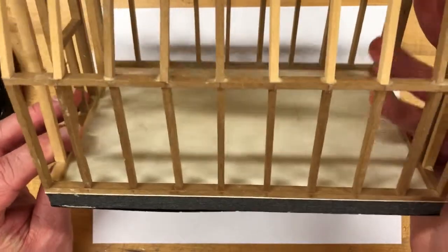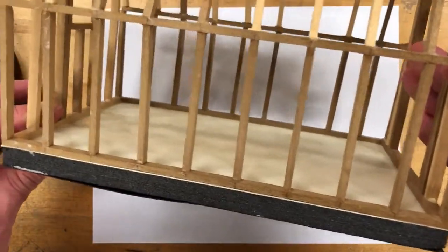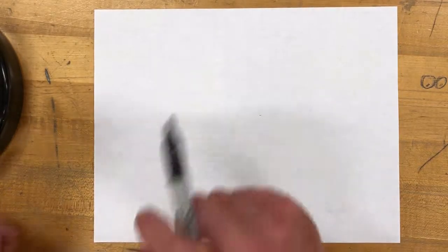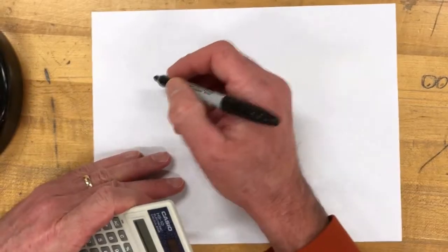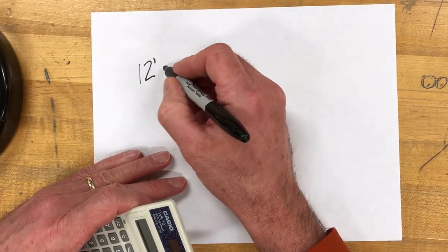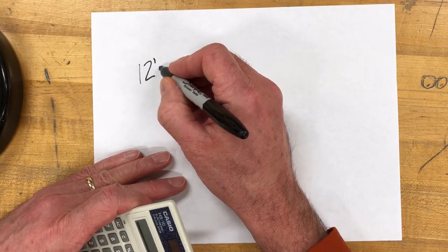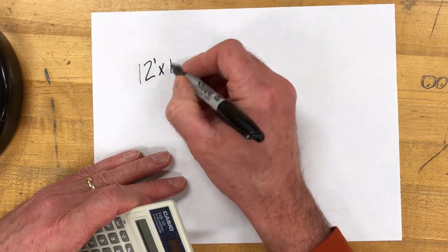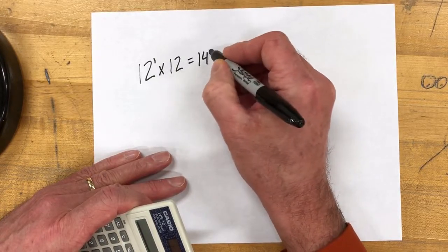Okay, as I said earlier, we're going to have a little bit of discussion about how many studs we're going to need along this wall system right here. The way we do that is we know that this wall system is 12 feet long, and that the stud spacing is exactly 16 inches apart. So we're going to have to do some quick calculations here. I know that the barn is 12 feet long, and if I find out how many inches, I'm going to multiply that by 12, and that'll give me 144 inches.